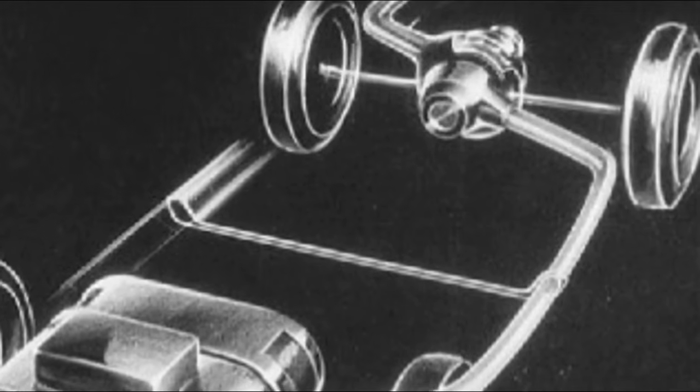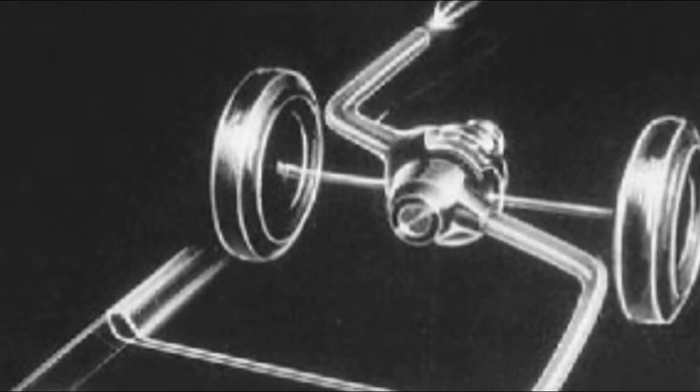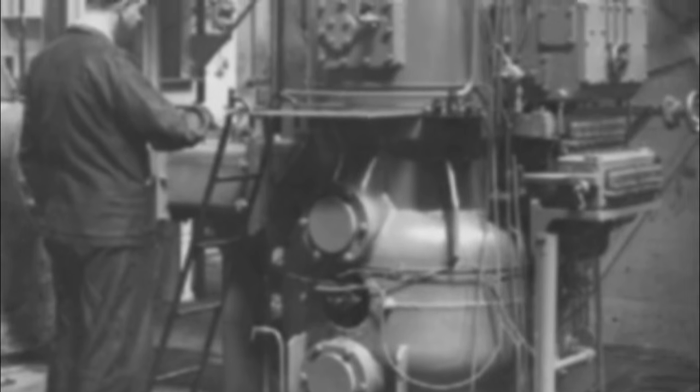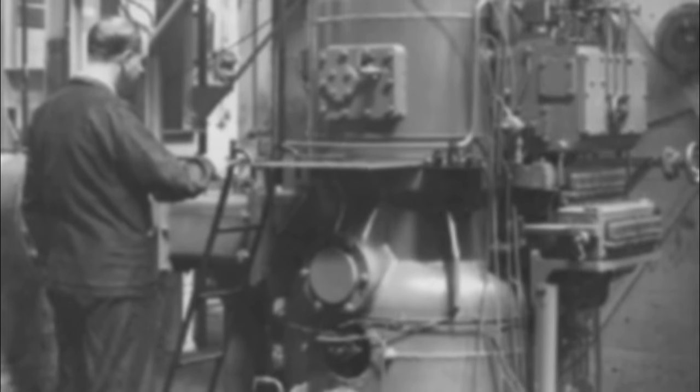The gas generator could be installed under the hood, and the turbine somewhere in the transmission, connected by a gas line. Since the piston speed during engine startup was close to nominal, the compression ratio at this point reached 50:1, eliminating the need for preheaters at low ambient temperatures. High compression temperatures and pressures, as well as excellent starting characteristics, ensured reliable operation of the tractor's turbo-piston engine on any liquid fuel, from 100-octane gasoline to high-sulfur fuel oil.